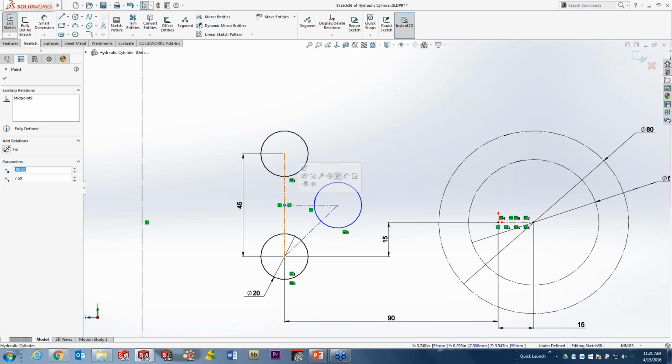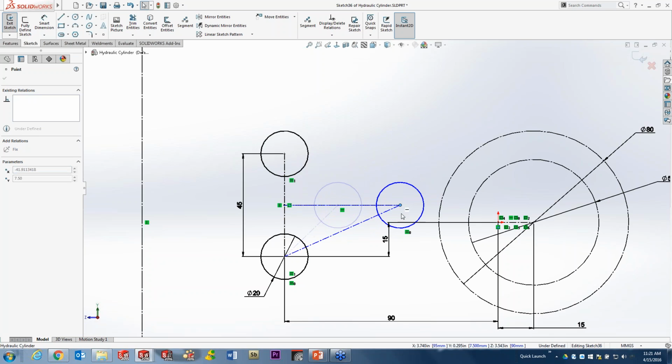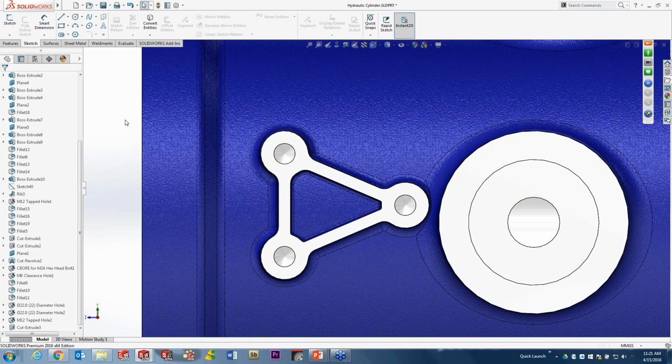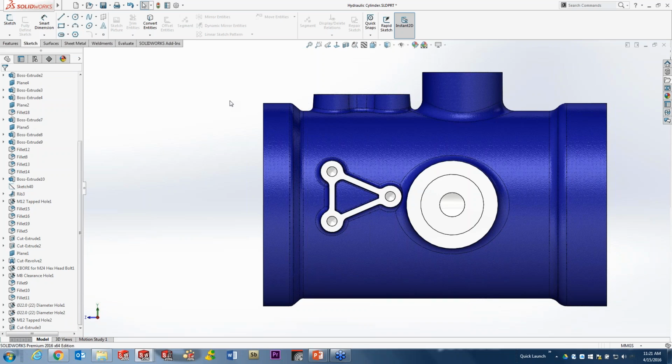Now I can easily reattach this to somewhere else, and I didn't have to delete and redo anything. I just had to have it let go of what is essentially a merged point. It allows me to then detach it and move it somewhere else. So that's going to save a lot of trouble, again, when it comes to those situations where a lot of people didn't realize that when you draw a rectangle, the corners of those rectangles don't have relationships. They are merged points, and there's no way to detach those aside from trimming and getting those things out of your way.